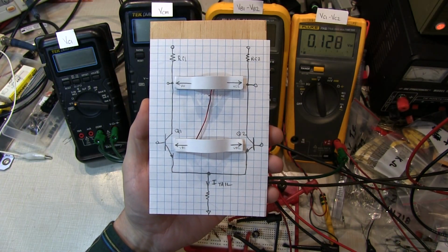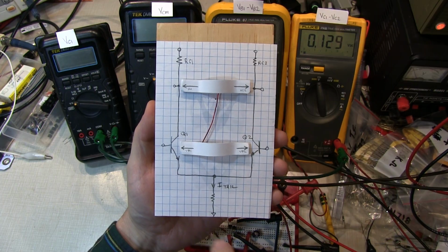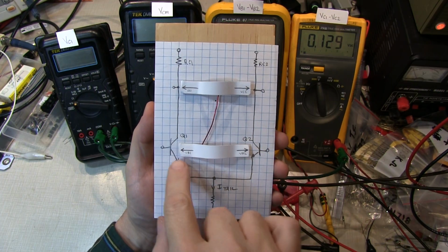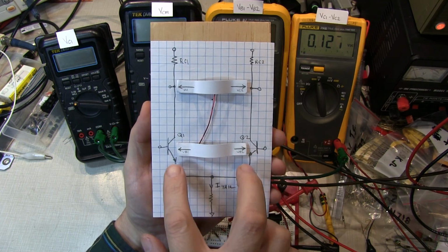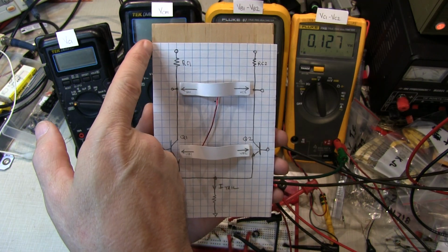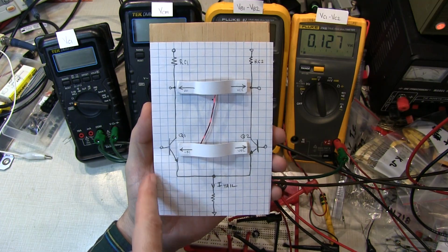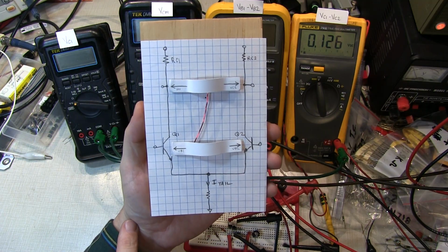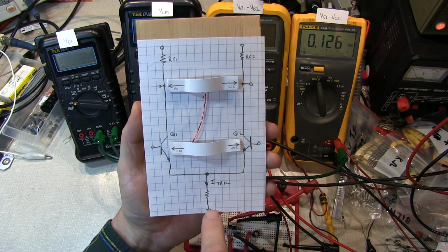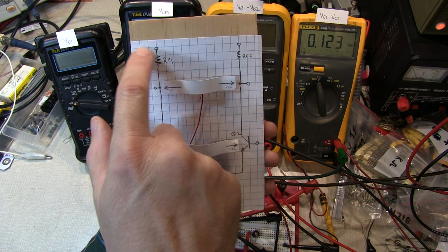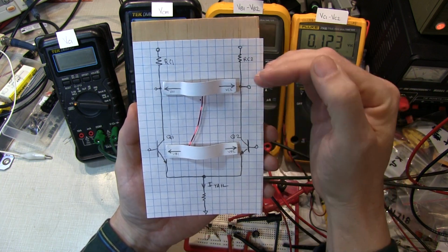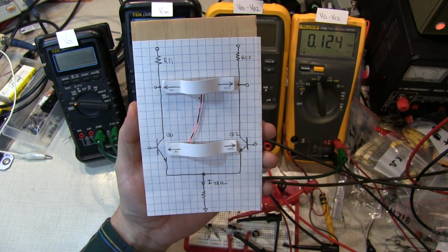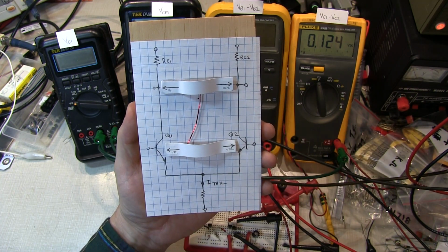Here's my little mechanical simulator to show you what's going on. So here's my diff amp, Q1, Q2, the two load resistors, the tail current here. Let's imagine that the vertical axis of this piece of paper represents volts, where I'm at 0 volts down here and 9 volts up here at the top. So you can almost think of the elevation of where these little pointers are pointing as the voltage at each of those nodes.